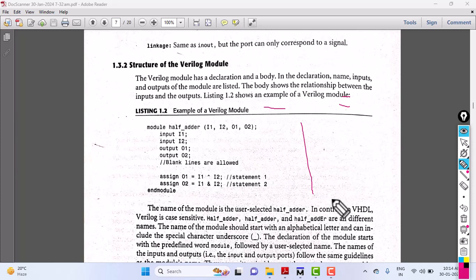One is the top level block diagram. My entire idea is conceptualized in the top level block diagram. And when you go to the micro sub levels, every level should be defined first on the paper itself. Then you will get a complete picture when you reach the micro levels, with all wire connections and all block diagrams, even imaginary blocks you should write. Understand here? You will understand the complete picture of your design. Once the complete idea is there on paper, then you can identify the proper tool and start coding them, one by one.